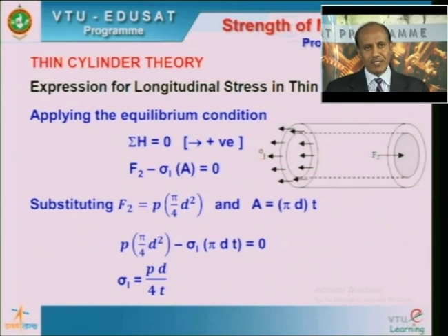As the internal diameter increases, the longitudinal stress increases. As the thickness increases, the longitudinal stress decreases. Please remember the expression for the longitudinal stress, that is P d by 4T.